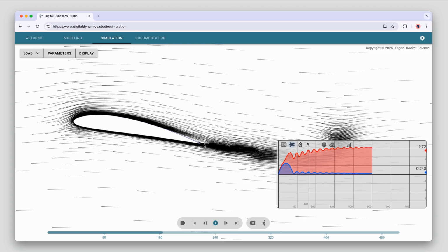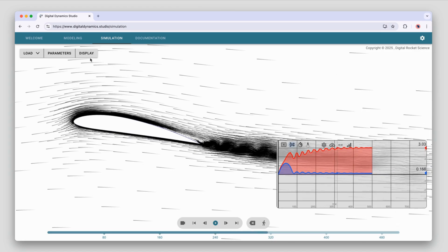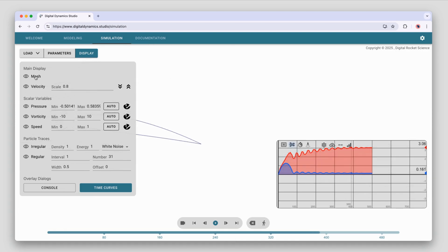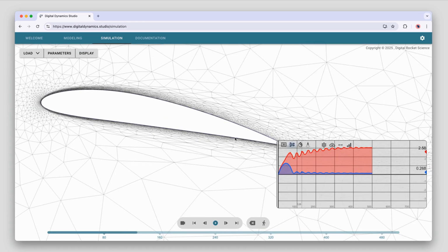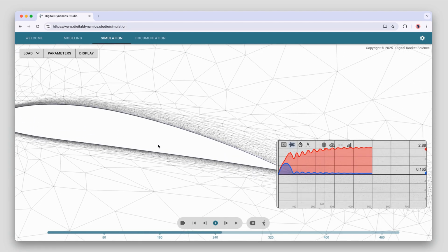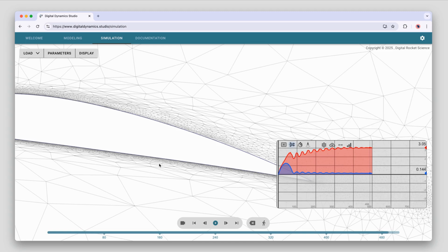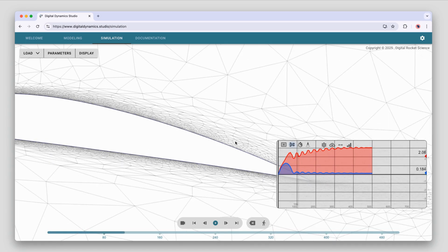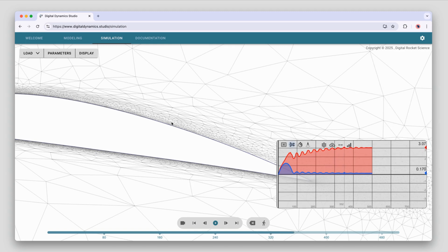That's probably because our viscosity is a little bit too high, and to some extent, the size of the mesh. In those locations, there are very thin boundary layer features along the boundaries, and the adaptive framework is doing the best it can to add small elements in those locations, but it's just not small enough to capture the boundary layer accurately.